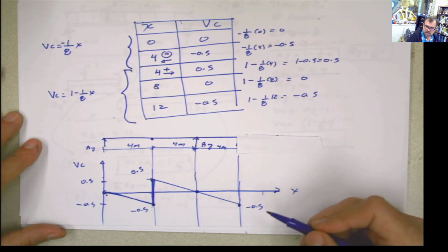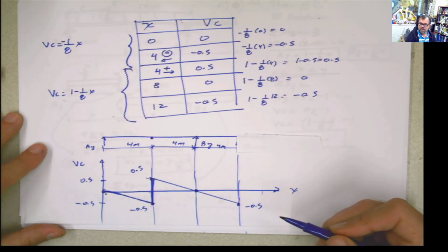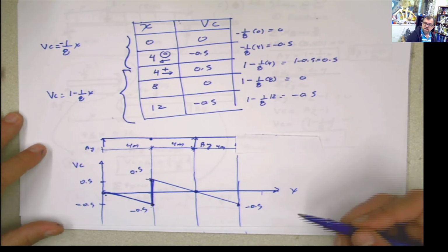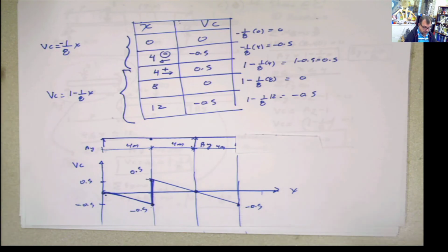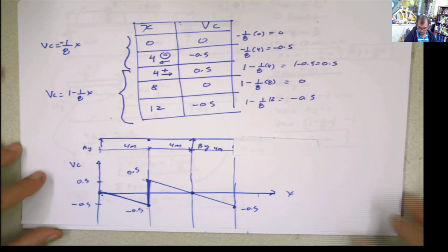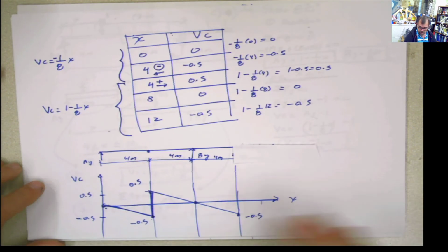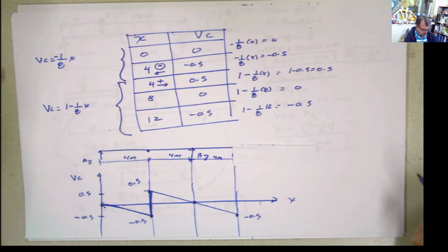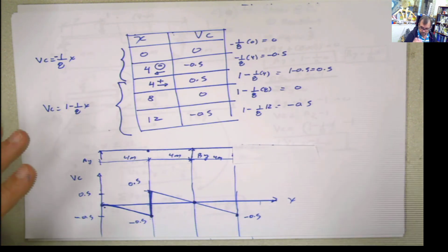Now same. If you are, for example, designing stirrups, I don't know, or designing something where you need the maximum shear happening in that element, you can calculate it with this. In the case of shear, within my applications at least, positive or negative doesn't make a big difference. But the absolute value is very important. The only difference between positive or negative shear is when you use it for calculating the moment. Okay, shear at C, done.